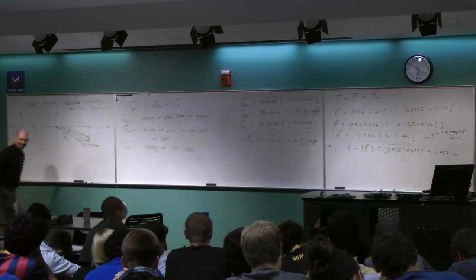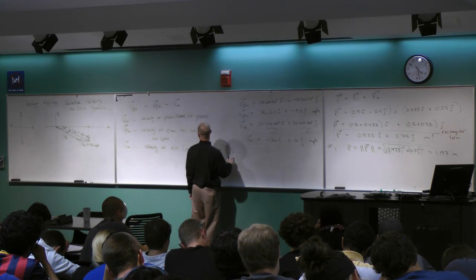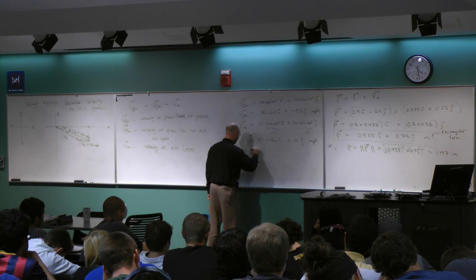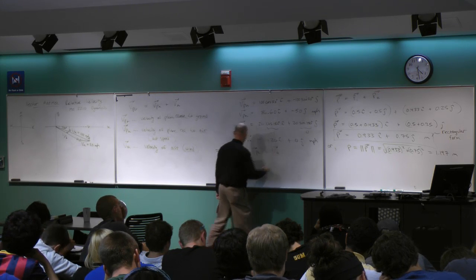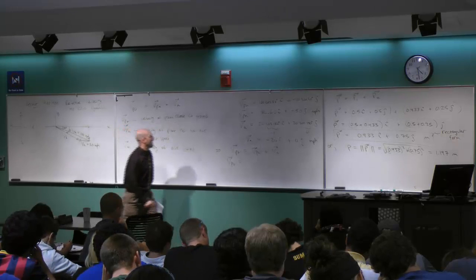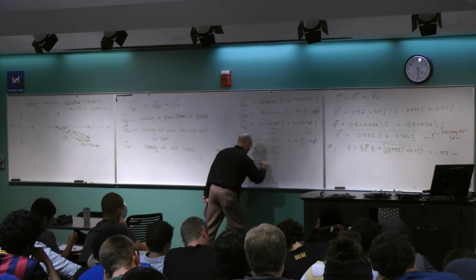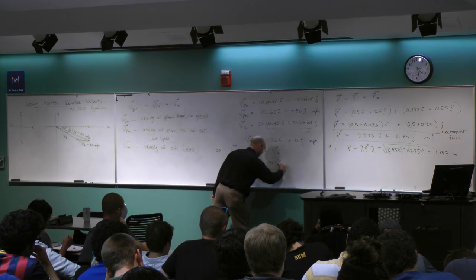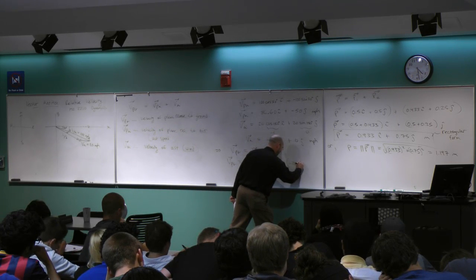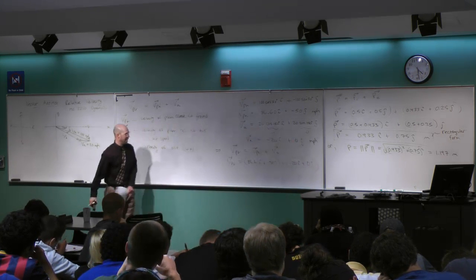So then to get the total, I wrote down the two vectors. I want the total answer, which is VPG, the sum of VPA plus VA. I just plug in the numbers. VPG is VPA, I got 86.6i minus 50j, so plus negative 50j. And then I got VA, which is minus 20i plus 0j. And so I add up those numbers.